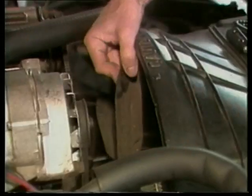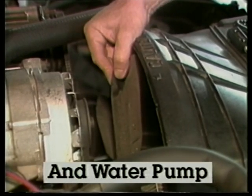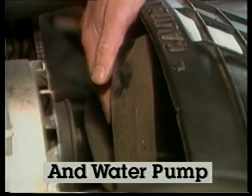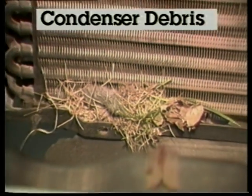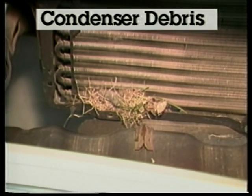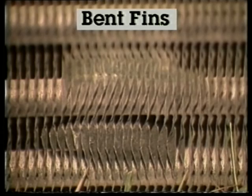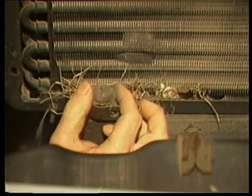To check for a bad water pump, wiggle the fan or pump pulley back and forth while watching for loose water pump bearings. An overheating engine could affect air conditioning system operation. Inspect the condition of the condenser. Clean out any debris that could block airflow through the unit. Check for bent fins and other damage that could upset normal condenser action. Blockage is common when a car is driven on country roads.